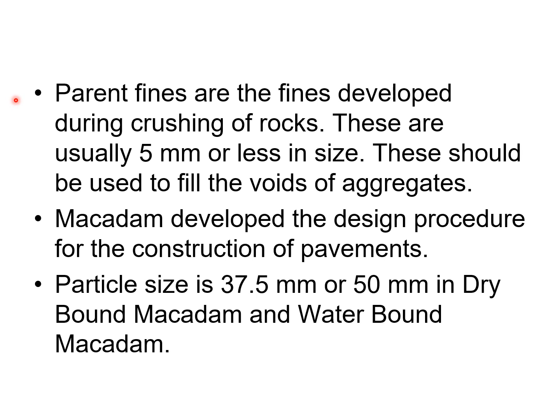Parent fines are the fines developed during crushing of rocks. These are usually 5 mm or less in size. These should be used to fill the voids of aggregate. Macadam developed the design procedure for the construction of pavement. Particle size is 37.5 mm or 50 mm in dry-bound macadam and water-bound macadam. So these are the two typical particle sizes for the dry-bound macadam and the water-bound macadam.